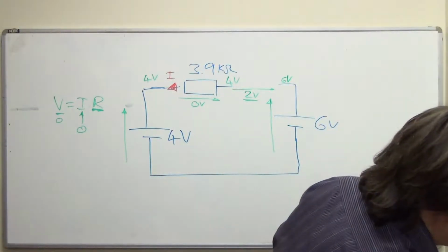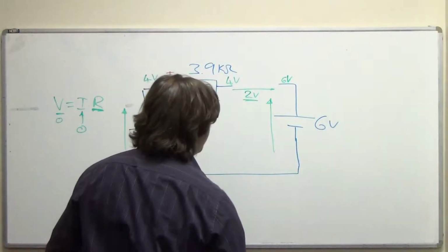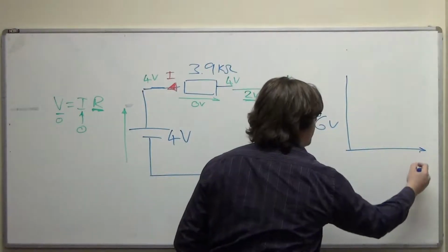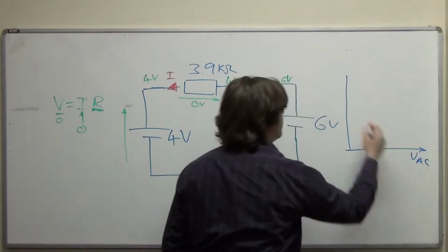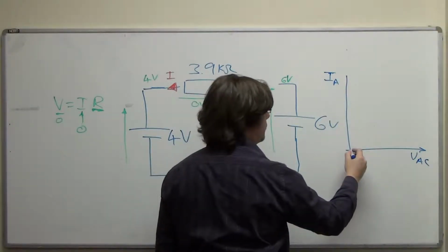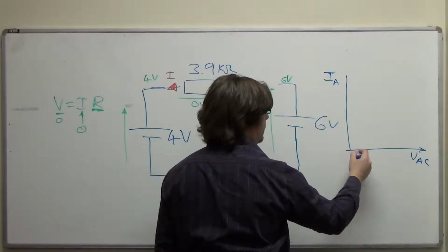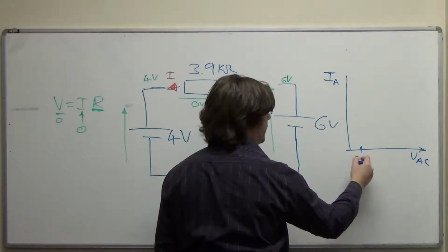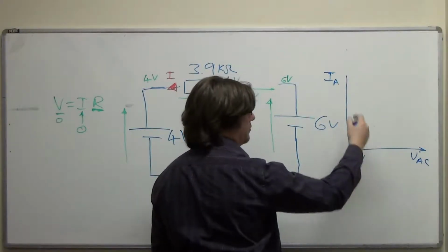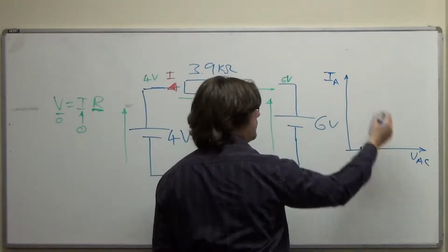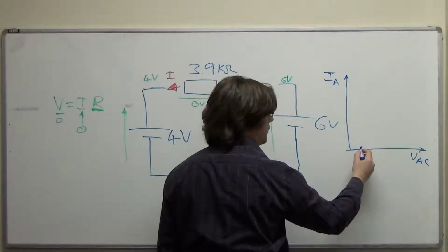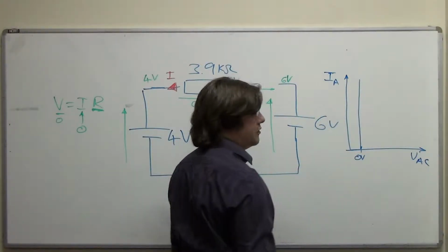So in terms of our diode model, we had some diode models, and one of them was, this is VA, anode to cathode, and this is anode current. We had one model that was, if I say 0 volts is here, and this is minus a couple, just to bring it off the axis, reverse bias, nothing, nothing, nothing, turn on immediately.